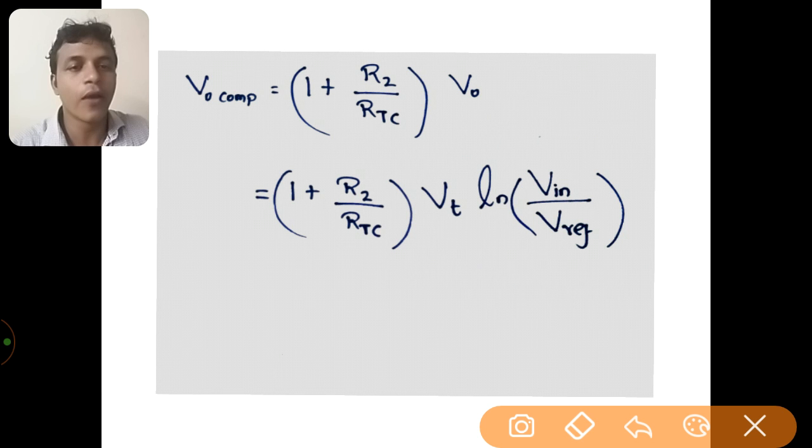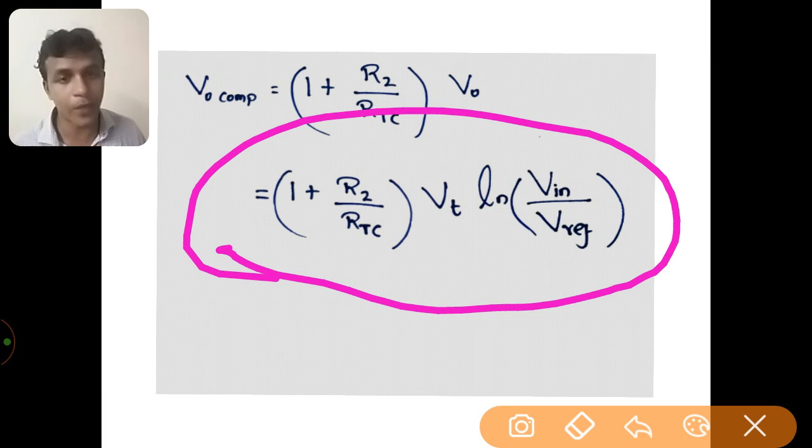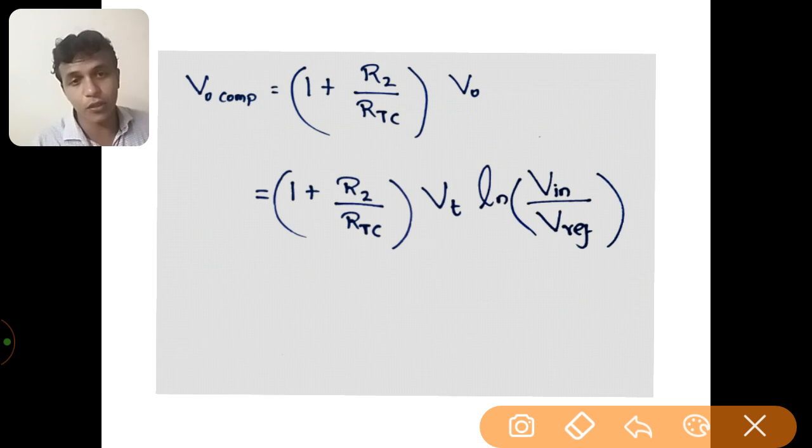So finally, the temperature compensated output. Is the conclusion that the temperature dependent component is eradicated here? No, because the saturation current, one of the temperature dependent components, is eradicated. The saturation current is not there, so we have cancelled it out, but the thermal voltage is still there. The temperature dependence of the circuit remains in the form of the thermal voltage, and that can be eradicated by using this circuit.